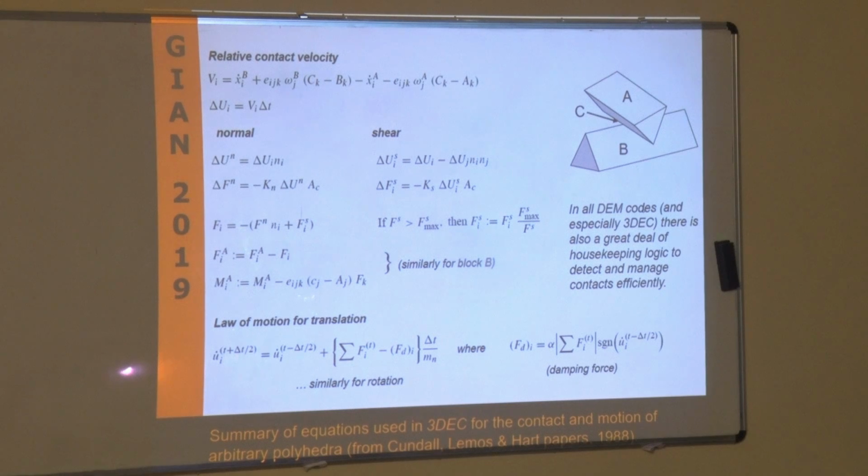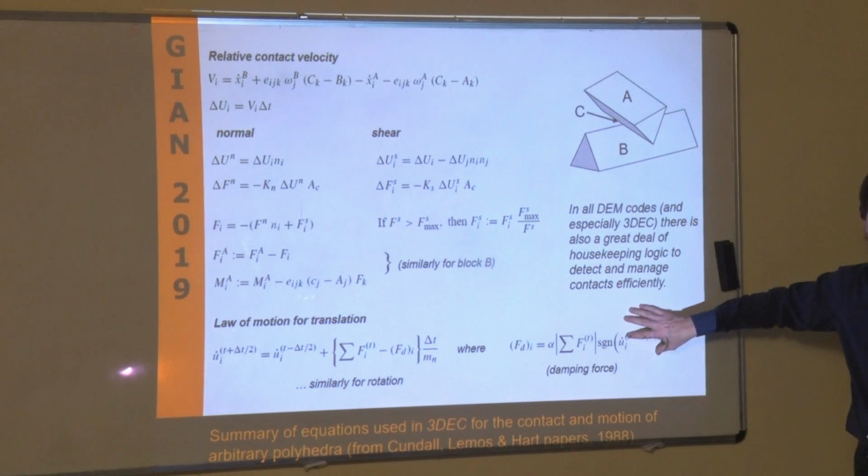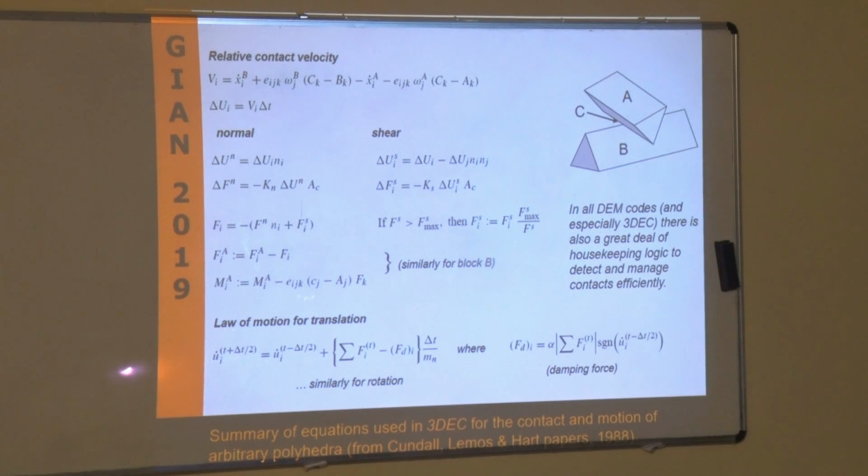That means that time is embedded in the equation and we know how the system behaves with time. So that's a big difference. This is time explicit, while most of the other finite element codes like FLAC are time implicit. So time is really embedded in the solver.